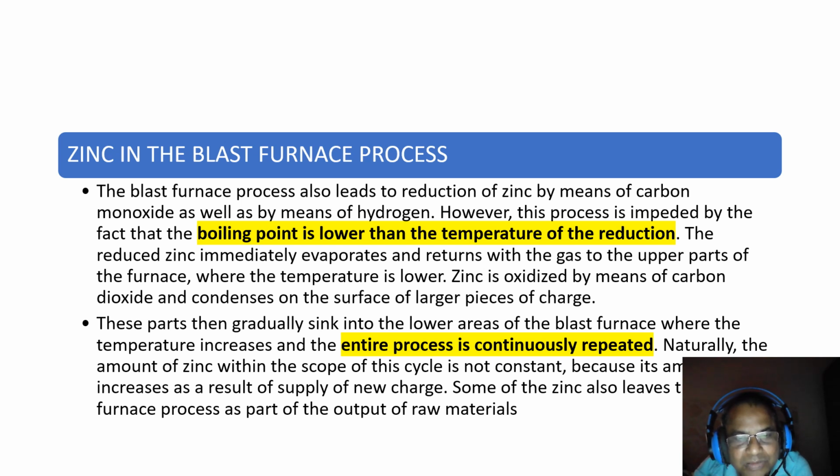And once this zinc becomes condensed on the refractory of the low temperature stack area, it forms an accretion, or we can say a deposit.